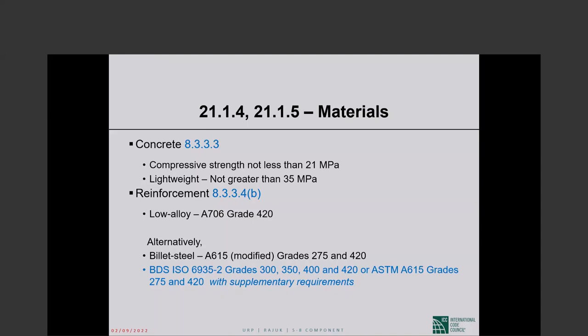That limit used to be a bit lower, and has been brought up in view of more test results being available. It is quite conceivable that with more test results coming, that limit will be adjusted. But up until now, I mean 2022, that limit has held at 35 MPa. That hasn't changed even in ACI 318-19.